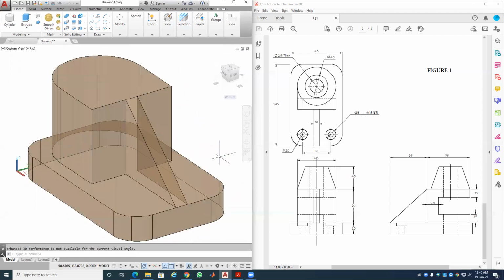All right, now let's do this part where we have this countersink, counterbore hole. For the head you have 18, and the depth is 5. So all these are in millimeters. So go ahead and change the layer. You don't want to get confused.